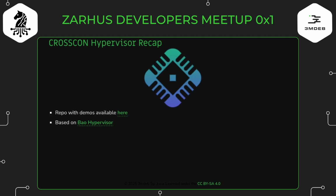So let's talk a little bit about the constraints of the current setup. Right now, the demo for the Raspberry Pi 4 uses a minimalist Buildroot initramfs, and this makes it sort of difficult to work with the trusted apps. We always try to focus on solutions with Yocto, and it's really easy there to just add a new recipe for any tool that you need. You also have access to a lot of layers that provide those recipes for a lot of stuff that we may need in the future. It's a lot more convenient that way with Yocto, and we avoid cross-compiling things so that they work.